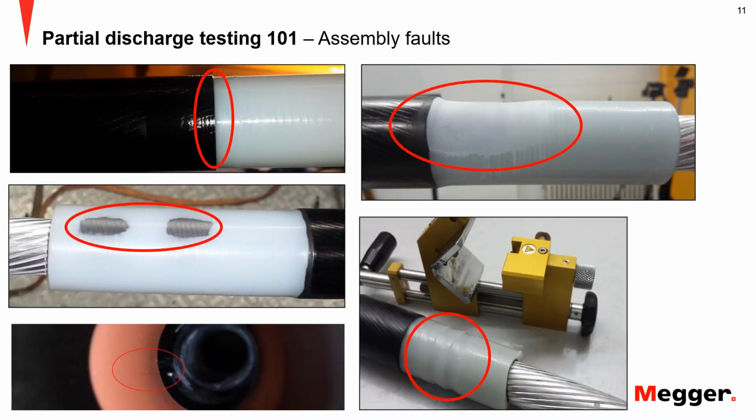In terms of failures, typical failures, just some pictures. Anything here would sooner or later lead to a failure of the asset due to partial discharge activity. So you can see incorrect sanding, incorrect cutbacks, pollution and contamination, cuts into the insulation, slipped off with the knife. So anything is possible. And believe me, everything is possible in the field in this case. These things exist. They're not just some academic exercises. This is kind of what we see more and more in the field everywhere, specifically on wind farms.